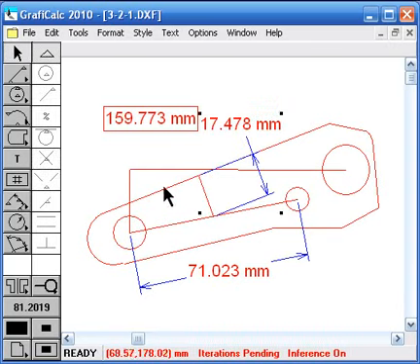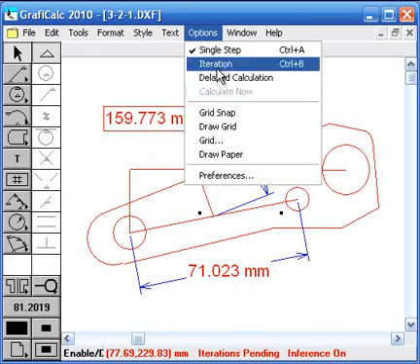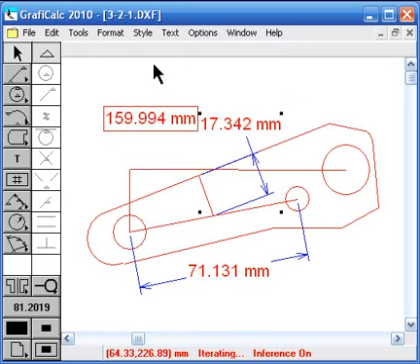So you can attach the calipers to anywhere that you wish and measure the linear, angular, and radial dimensions, as well as use all the graphical calculation built-in functions to extract values from the model, and then apply really fast Monte Carlo analysis to a part to see if it can be manufactured, or to an assembly to make sure it will work as expected.